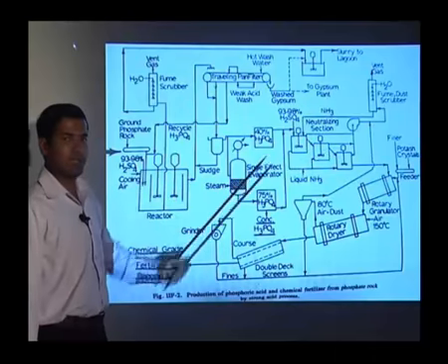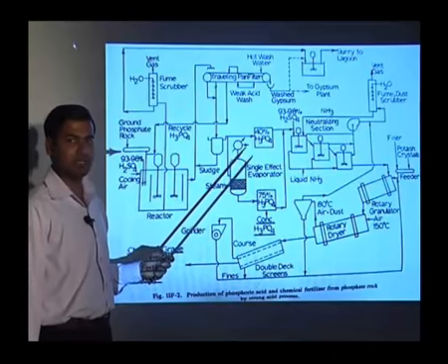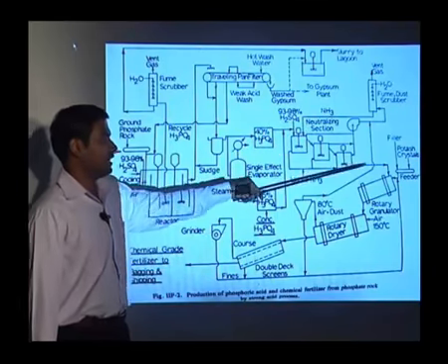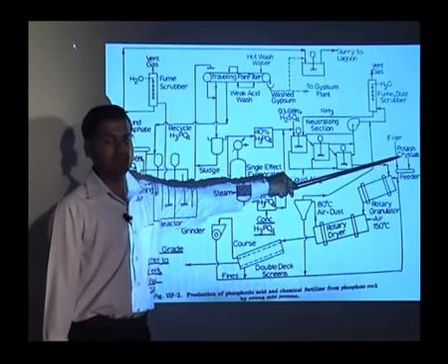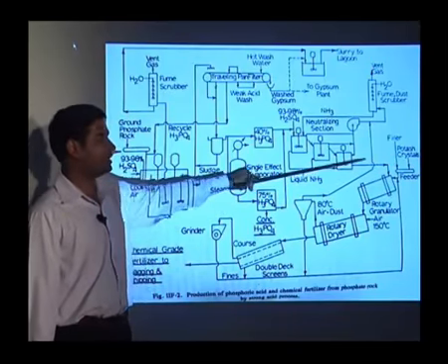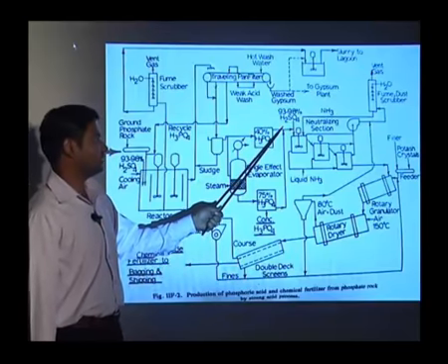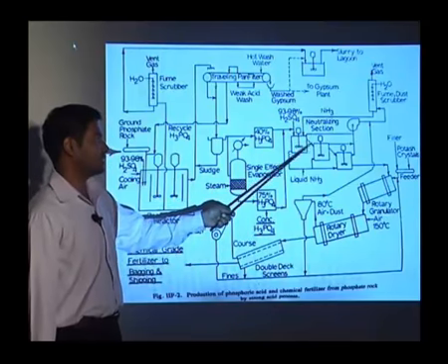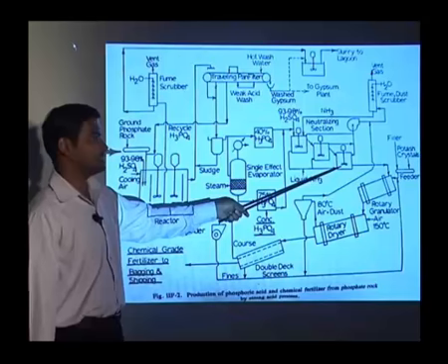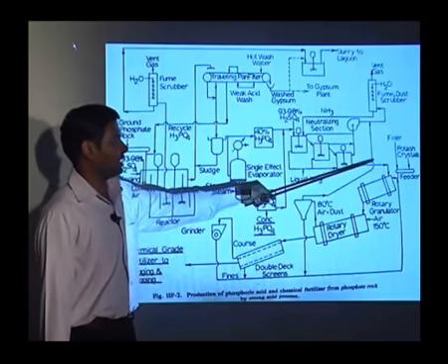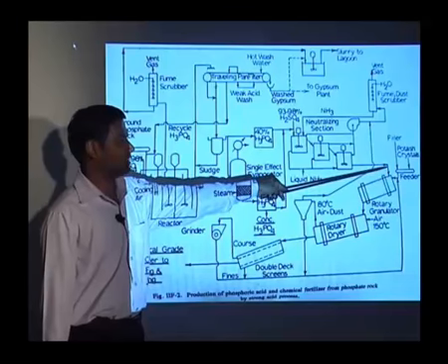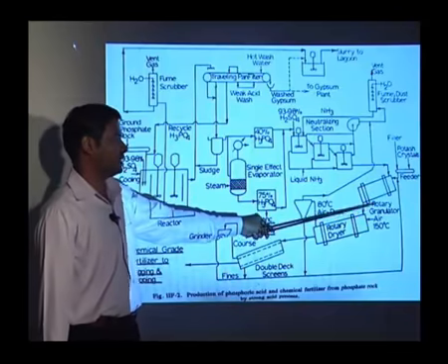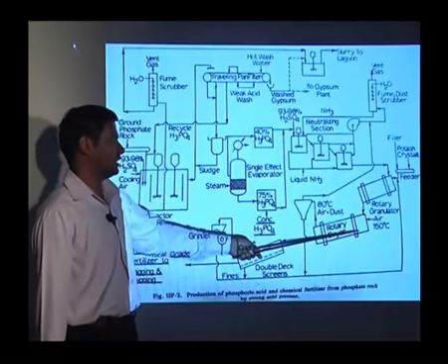We have seen earlier NPK, that we require nitrogen, phosphorus and potassium. So here we are neutralizing with the help of ammonia, and then we add potash crystal to have the potassium content in it. The lower grade phosphoric acid, or the phosphoric acid water we have stored, we will neutralize in the neutralizing section in multiple reactors or neutralizing tanks, and we get the final grade fertilizer. We add potash crystal to have the KCl content in it, then a rotary granulator to make the granules, and then it is dried in the rotary dryer.